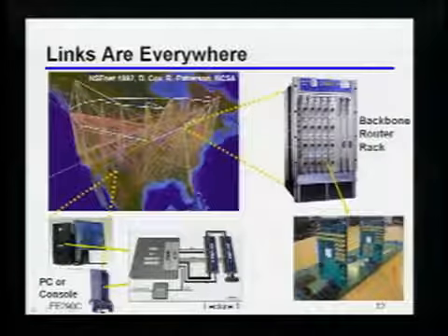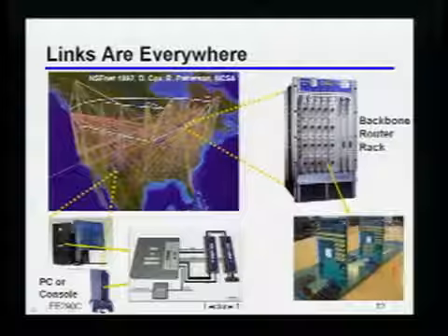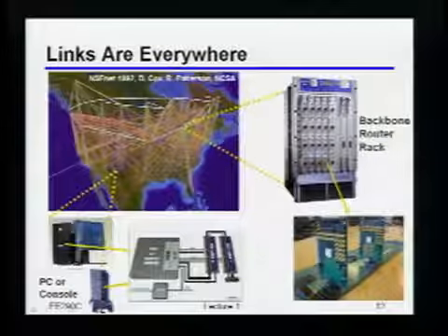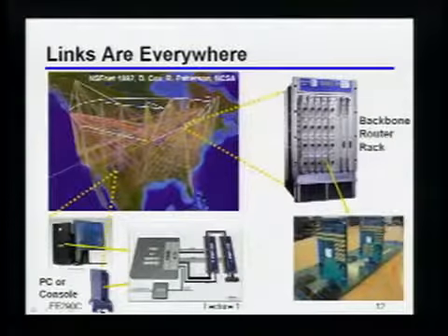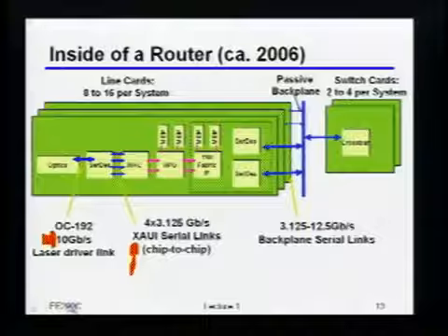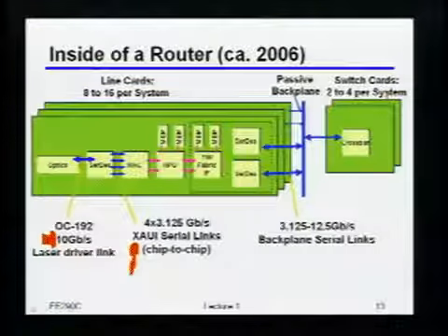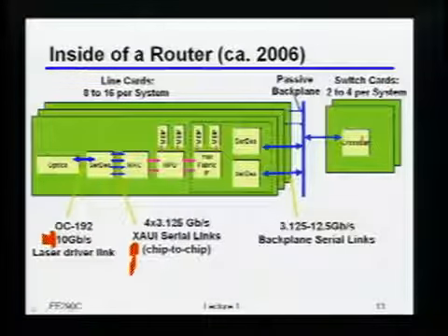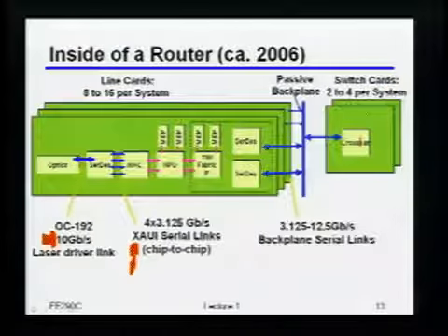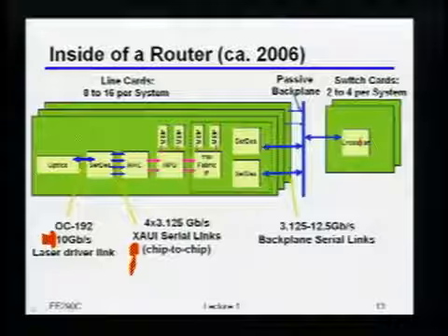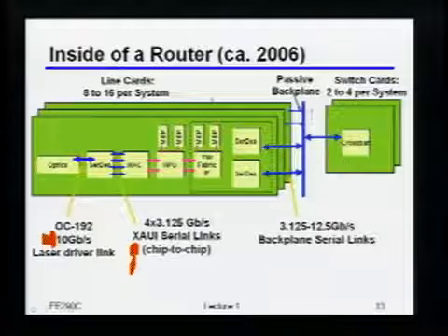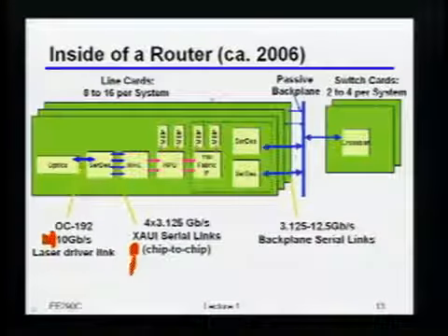Literally all it's doing is it's a whole bunch of wires connecting these different switch cards to each other, or these different line cards to each other. Okay? And since I already mentioned it, you've also got these so-called switch cards. Usually you would send all of your data to the switch card, and then the switch card would say, oh, okay, this data came from here and is supposed to go there, so it'll forward it over to the other line card to make that full connection.